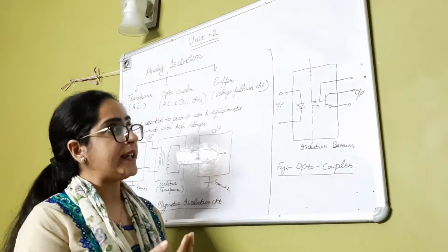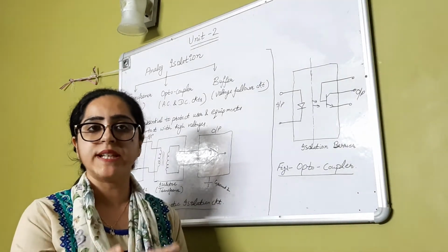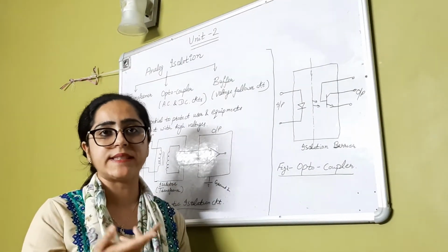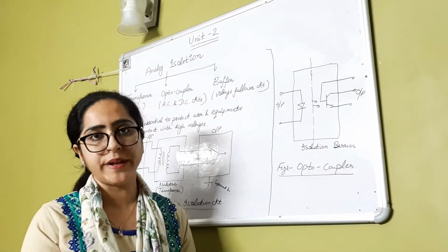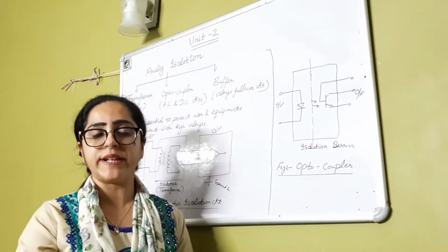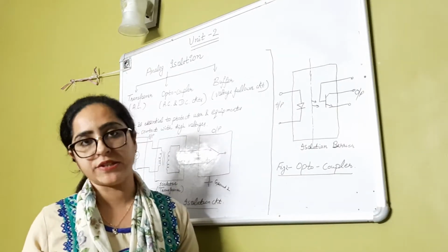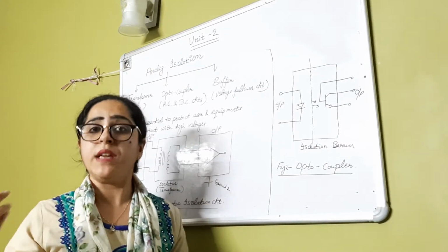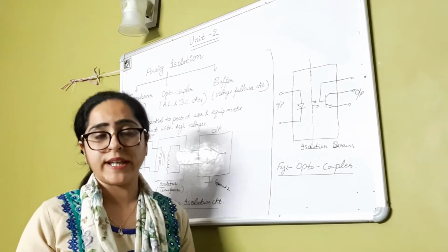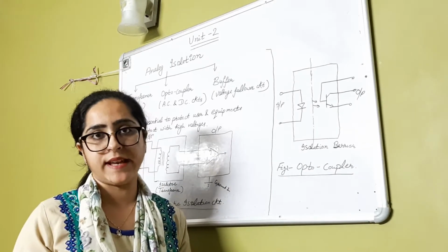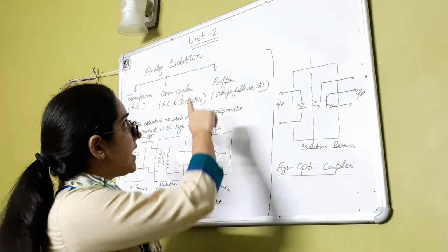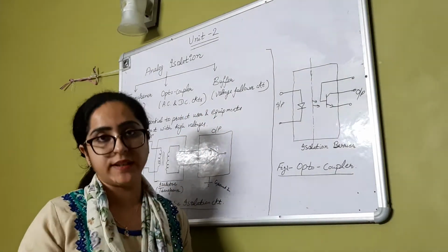So certain high voltage spikes or transients can harm the instrument, as well as, through the instrument, we are monitoring the health of the patient. So it can somehow harm the patient also, or can cause certain accidents there itself. For that purpose, analog isolation is very much needed.